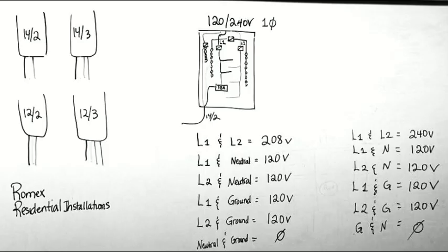So the minimum amount of circuits that we put in a house is 2. We'll stagger the lights around the house, and make sure that the customer has at least 2 circuits for lights. Because anything could fail, the panel could fail, everything is man-made and something could happen, so we wanna make sure that when we design our circuits, they're effective.